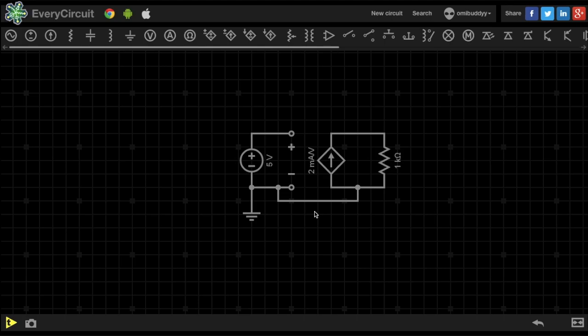On similar terms, you can also design a current amplifier, and the building blocks needed are going to be a current controlled voltage source and a current controlled current source. Like in the case of a voltage transducer, where we didn't want any current to flow from the transducer, on similar terms in a current transducer we want all of the current which is given by the transducer to affect the output, because input current is what we want to sense and amplify. From this we can conclude that voltage sources are likely to be open and current sources are likely to be short circuited when in use. Voltage transducers also are meant to be used when they are open circuited, and current transducers are meant to be used in short circuit condition.